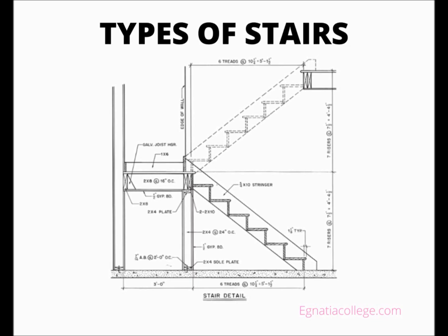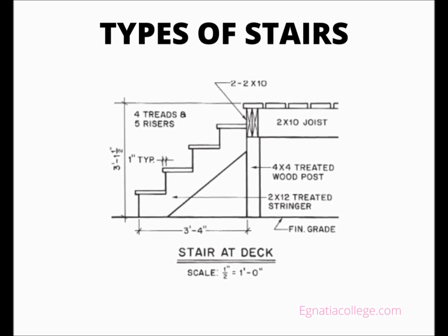Spiral stairs require the least floor space. They are made up of winder treads, usually supported by a center column. Temporary stairs used only during construction are usually of cruder construction. They are often made of 2x10 stringers with wooden cleats to support the treads. Service stairs in unoccupied spaces, such as a cellar, are often made of 2x12 open stringers with 2x10 treads. Stairs for exterior decks are also sometimes built with 2x12 open stringers. However, the carpenter should remember that these stairs are important to the overall appearance of the deck.